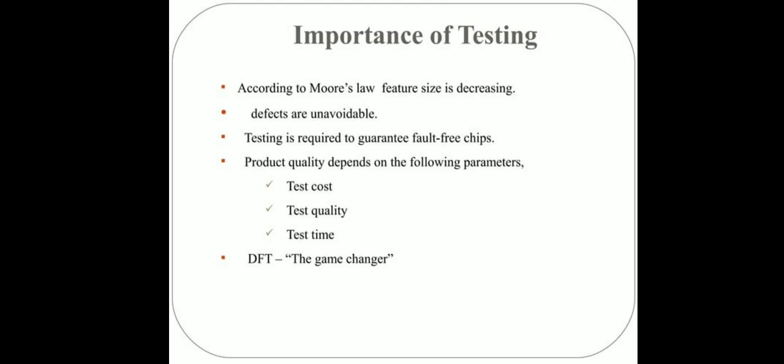In VLSI, design for testability is mainly used to make digital circuits easier to test during the manufacturing and debugging process. DFT in VLSI design involves incorporating additional circuitry and design features such as scan chains, built-in self-test circuits, and boundary scan cells into the chip design so that this facilitates testing.